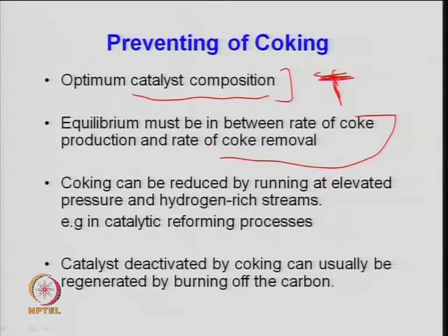If you are making a benchmark, then coke in the regenerated catalyst should be less than 0.1%, and the starting material may have around, say, 5%. So, how the carbon has to be removed from 5 to 0.1% needs to be calculated, and accordingly the sizing is to be done or the kinetics is to be discussed.